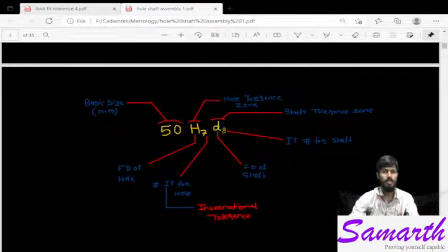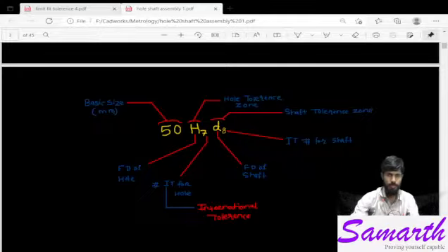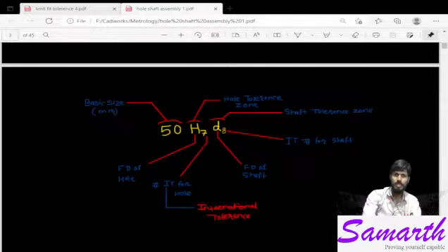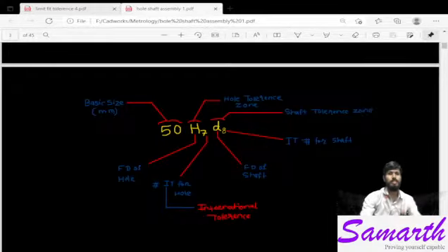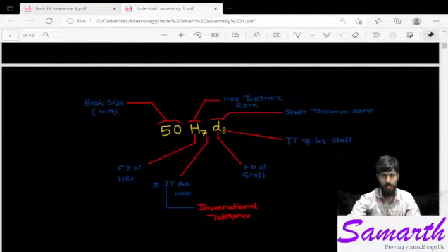Now the next one is the small d suffix 8. This is the shaft base, right? If small d is used, 8 is the international tolerance for the shaft. So we will find the tolerance values from one chart. I will show that chart to you first.